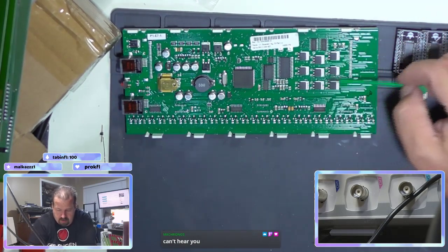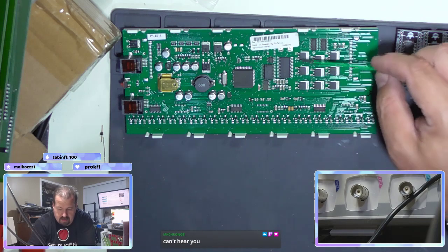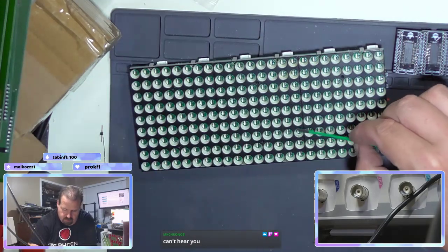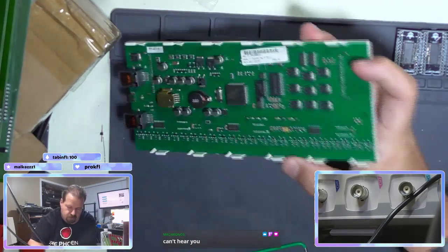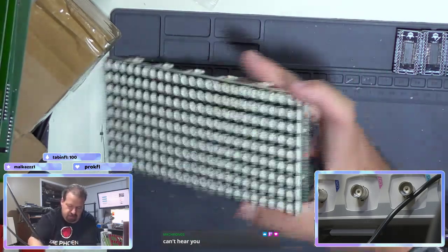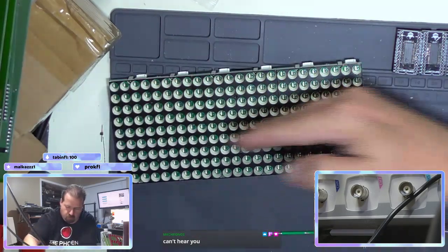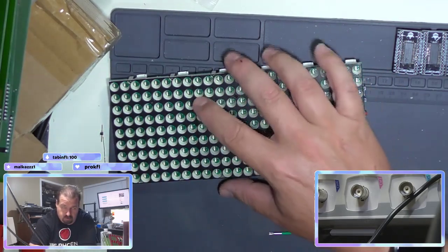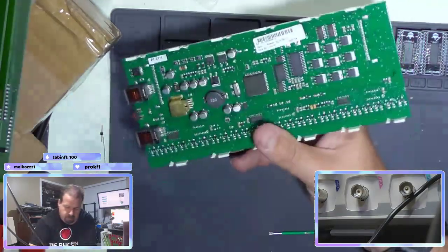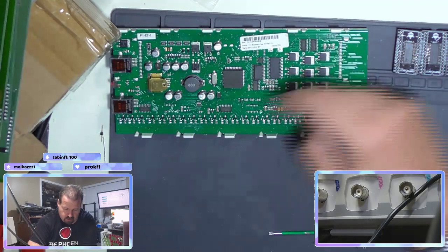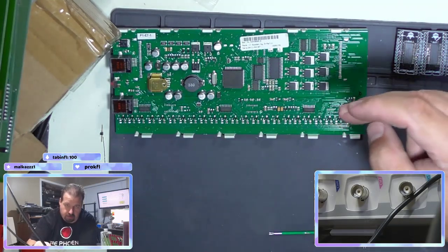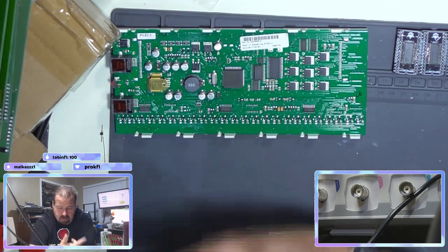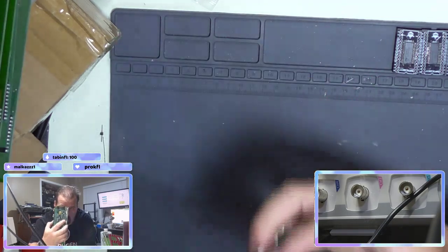And then up here, we have 1, 2, 3, 4, 5, 6, 7, 8, 9, which coincides with these 1, 2, 3, 4, 5, 6, 7, 8, 9. So this whole row is one big row. This is a more traditional board drive. You basically serial load it and then turn the column on, serial load it, turn the column on. So most of those tools online that generate the font tables work really well with this display.